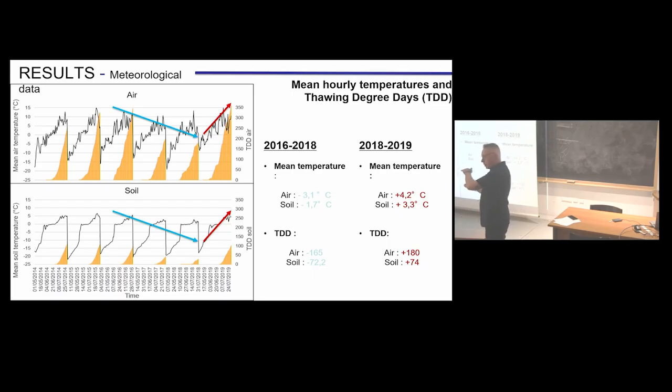Like we saw at the beginning of the course, the bottom of the active layer goes up. You create ice in this area, in 3 years, only 3 years. And then we have this very warm summer. So what happened? You get into the ice you just formed, you release that water, you have extra pore water pressure, and then you trigger landslides. So it happens, but when you see it everywhere, something must have happened.